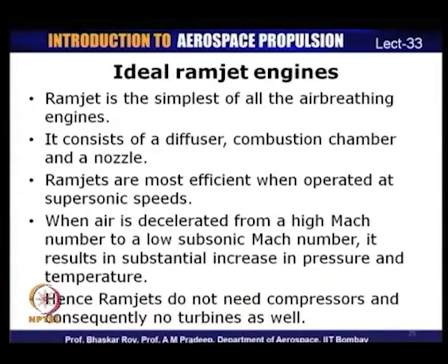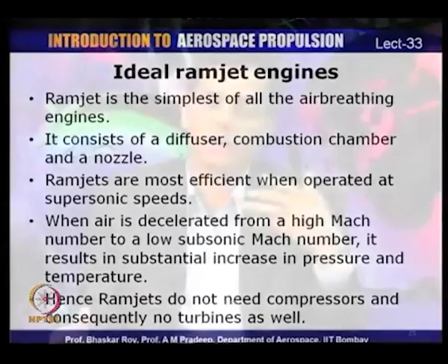Now, if you are already having such a high increase in pressure and temperature without the need of using a compressor, then you do not necessarily need a compressor and therefore, no turbines. And that is why ramjet is considered the simplest form of air breathing engine, because you do not have any turbo machinery present there, you do not have a compressor, you do not have a turbine. So, there are no rotating components there, and so since there are no rotating components in a ramjet, you can actually have very high temperatures in the